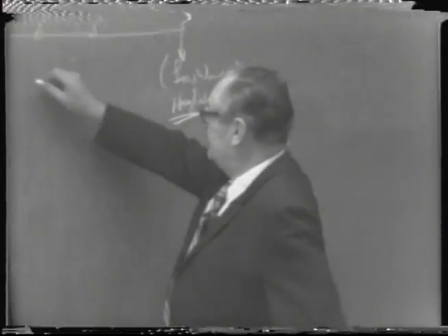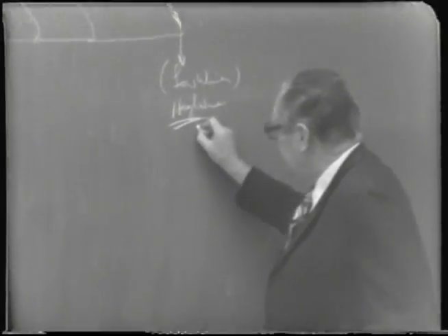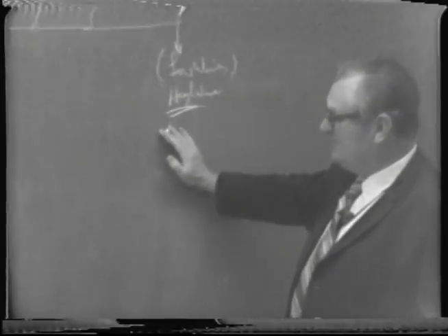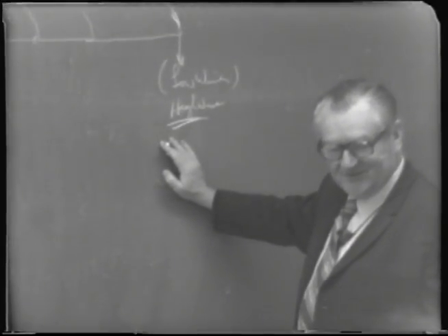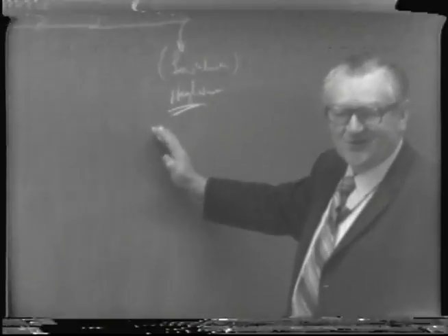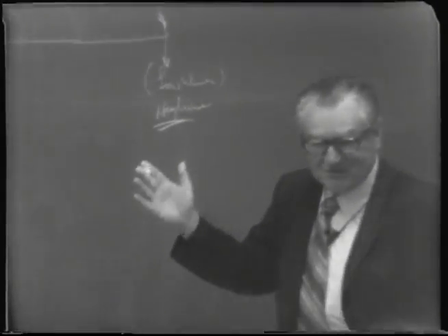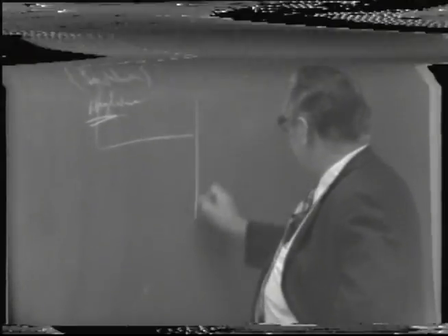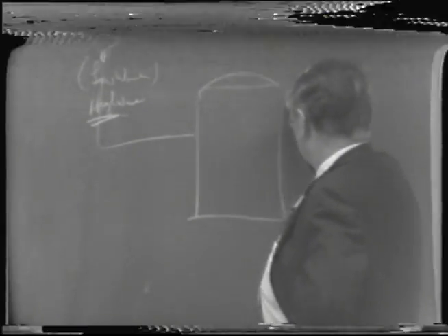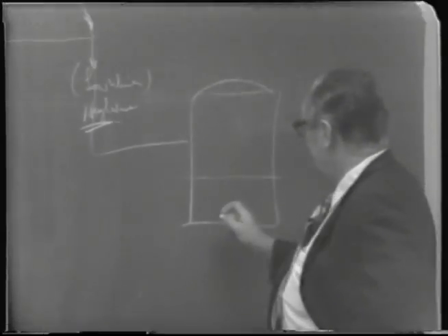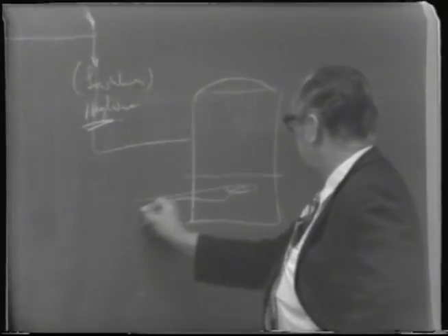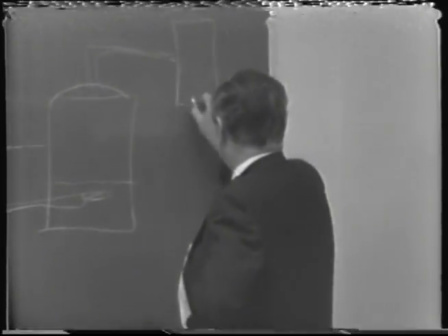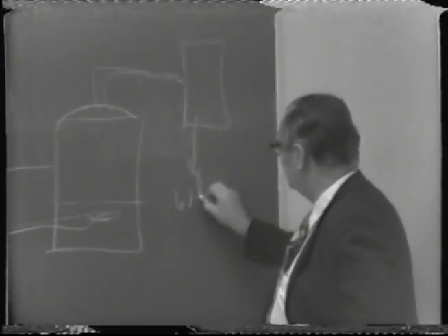But anyway, fundamentally, this material here is the basis material for bourbon. Then they run it through what they call a doubler, or sort of a continuous pot still, you might call it, a big, large place where they vaporize it one more stage. In other words, this might go into a large pot still, where they have a steam coil here, and this is re-vaporized and condensed, and this is whiskey distillate.